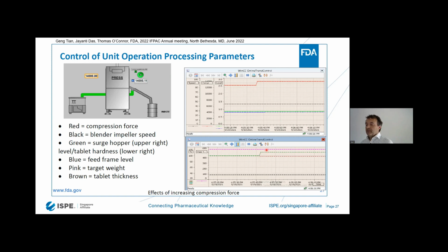So this is, I think, important because normally operator training systems focus on filling, heating up, cooling down, and so on. This is an operator training system that actually predicts what the effect is of operating conditions not only on process performance in terms of throughput, but also predicts quality attributes of, in this case, the tablet.